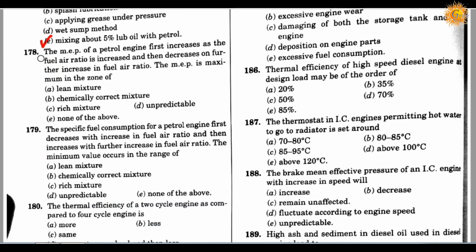Question number 178. The MEP of a petrol engine first increases as the fuel air ratio is increased and then decreases on further increase in the fuel air ratio.